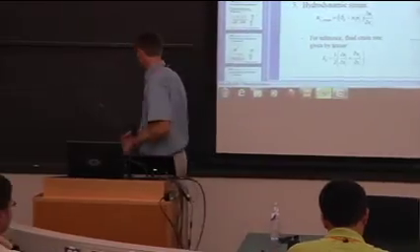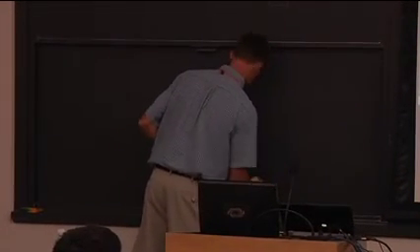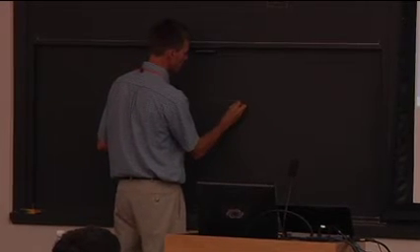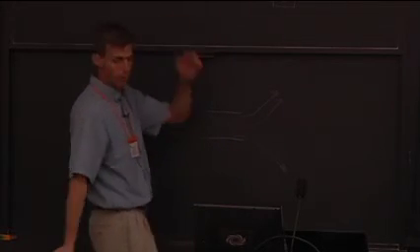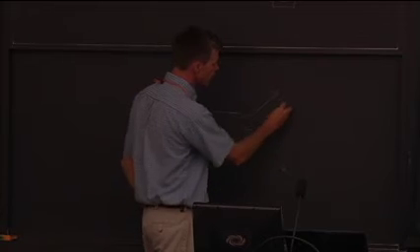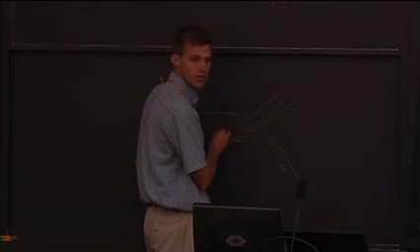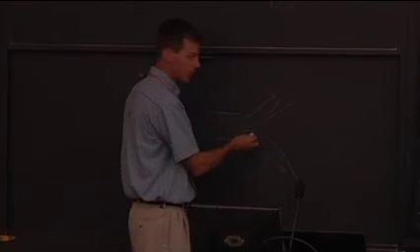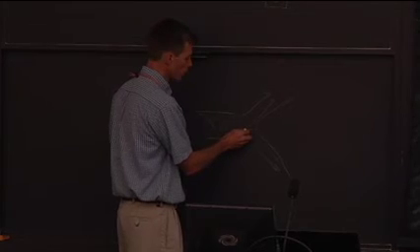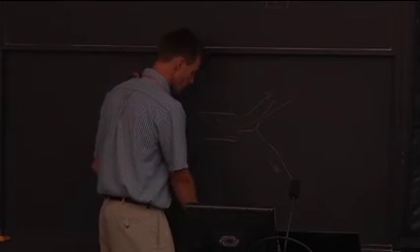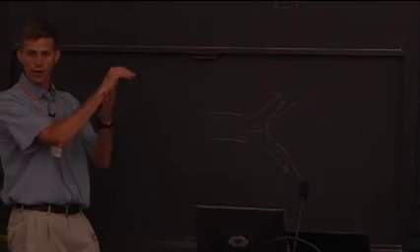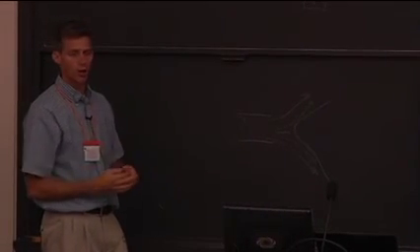However, one thing about swirl flows is they have very rapid divergence. So if I take a flow with a swirl that's below the critical level, the flow is going to very rapidly diverge. Because it's swirling, it just gets spun out by pure centrifugal force. And so you get a lot of deceleration. And what will happen is the flame can just find a spot where the flame speed matches the flow speed. It's actually stable. If the flow velocity drops, the flame can find a spot closer. If the flow velocity increases, it will just get pushed downstream. And so there are these stabilizing mechanisms. It actually turns out to be a really slick scientific device for making a flame just sit there in one reasonably well-defined region in space in a flow without shear.